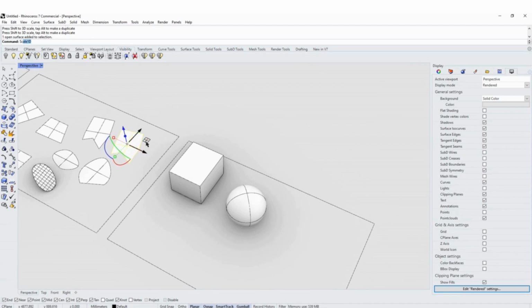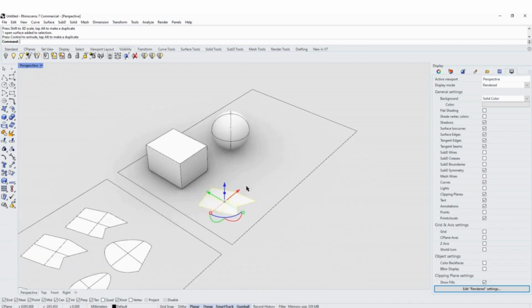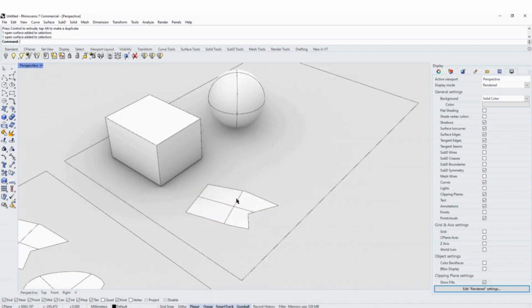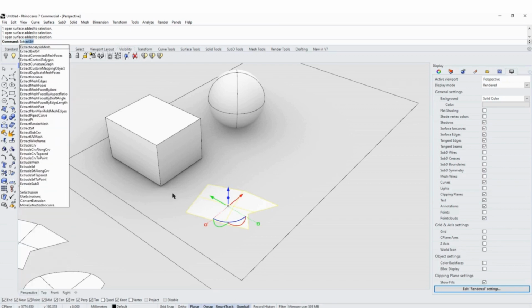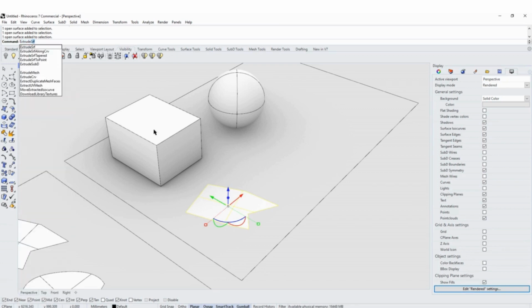There is another way to create our solids, and this is by actually using our surfaces. So let's say I go back here, I select one of our previous surfaces that I liked. So let's say this one, I create a copy right over here by clicking Alt. So there is a way to create from this one a perfect solid, and that is by extruding this surface.